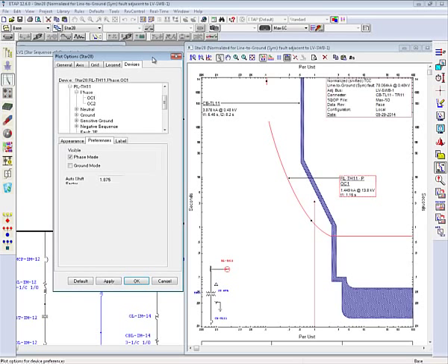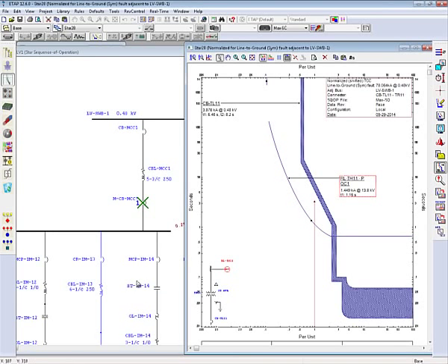So different shift factors for different protective devices, based on actual fault condition, will accurately depict the coordination between two protective devices. These examples showed how we can do protection and coordination in the present release of ETAP.